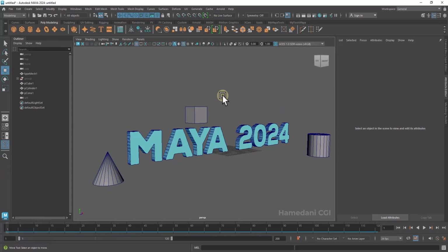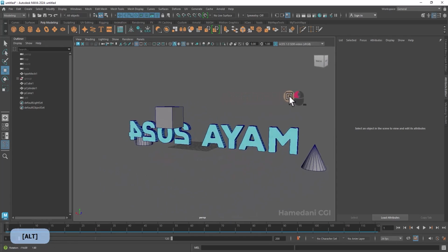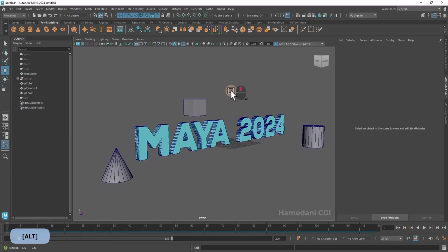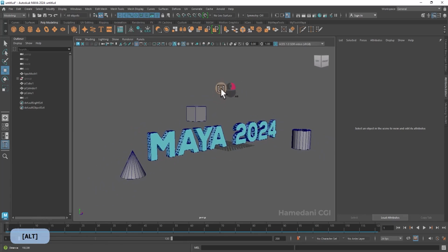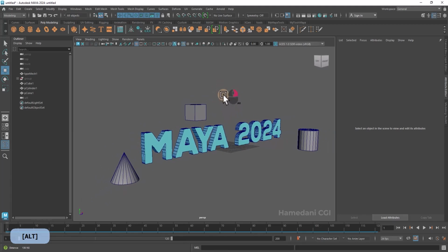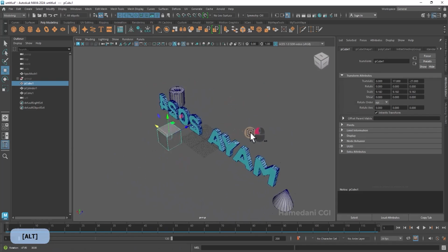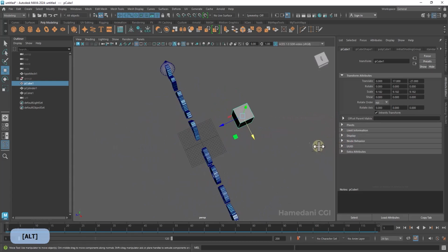And then I want to navigate in the viewport. When you hold Alt and the left mouse button, you can rotate. Hold Alt and the middle mouse button, you can pan. With the right mouse button, you can zoom in and zoom out. There are other keys. When you press F, it frames the object. When you press A, it frames all objects. When you change your viewport, like pan, zoom, and rotate, you can press Home and see your default viewport.